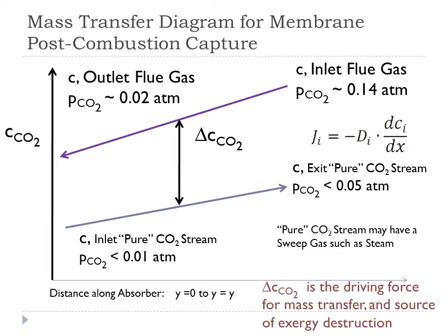than we would be if we didn't do the sweep and we're at 0.01 atmospheres or below. And as a reminder, when you're using a compressor, the amount of work is proportional to the logarithm of the pressure ratio. So if we have to get to 150, it'd be the logarithm of 150 divided by the starting pressure. If we can start at 0.05 atmospheres, that's a lot better than starting at 0.01 atmospheres. It's like logarithm of 5 better.